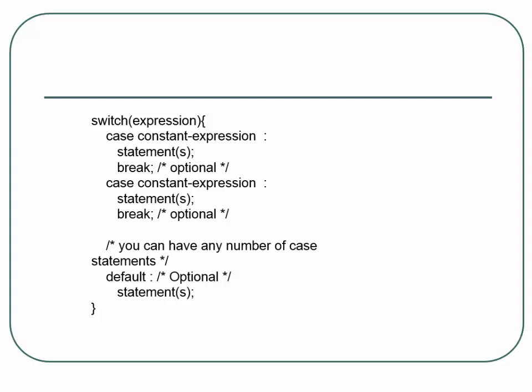Because switch case is the perfect way of doing a finite state machine. You just switch here, and then you can have your expression. You would typically put your current state in here. So here, case wash versus case idle. What do we want to happen in the idle mode? Well, we want to look at our inputs and determine what our next state is. So this is actually the way we typically would handle it.